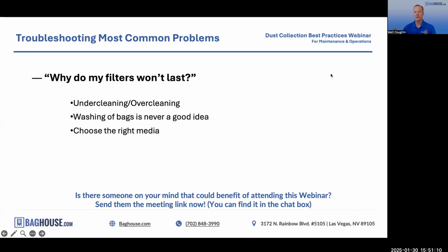There are various options for coatings for really fine filtration or higher efficiency filters. All those are options, and you should not ever just pick a bag that fits without knowing what it is, because if you over temp it, it will fail, or if you have moisture in your system, something like that. So the right filter media is critical.